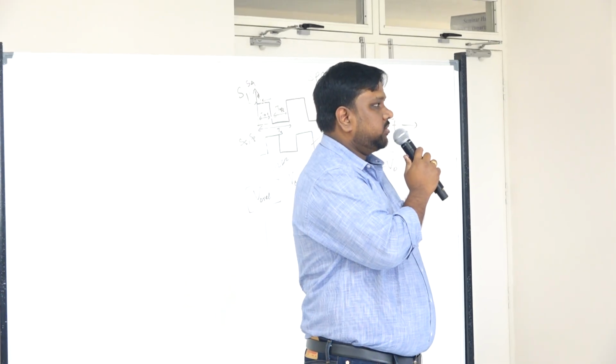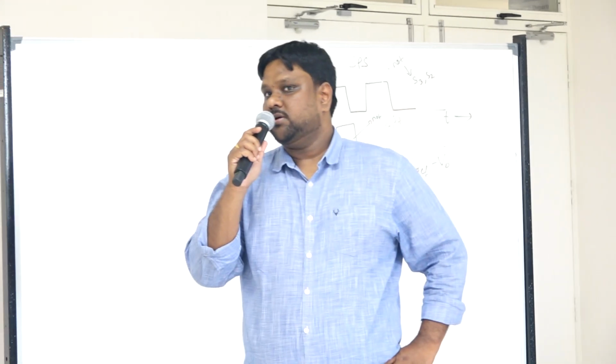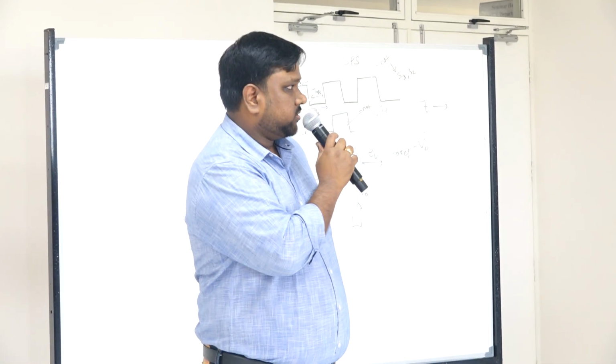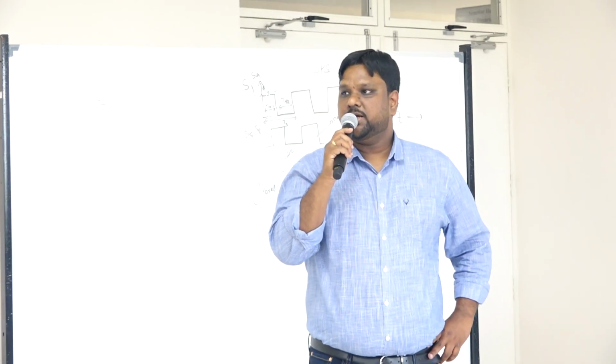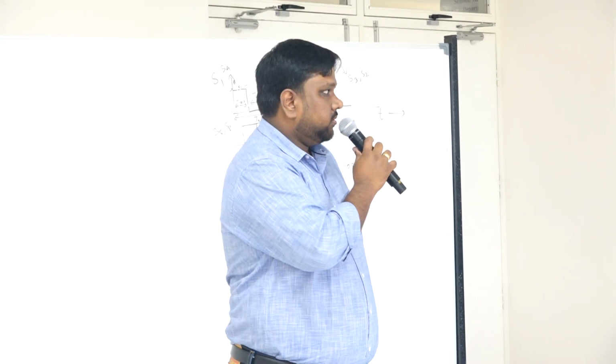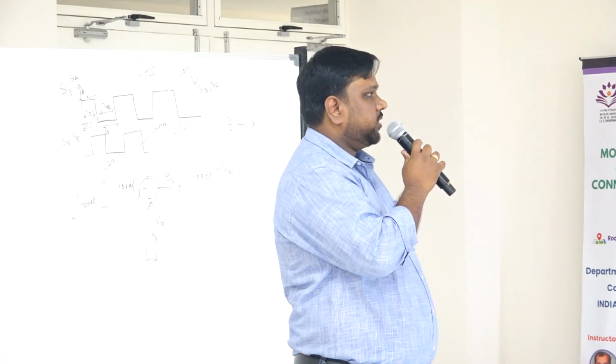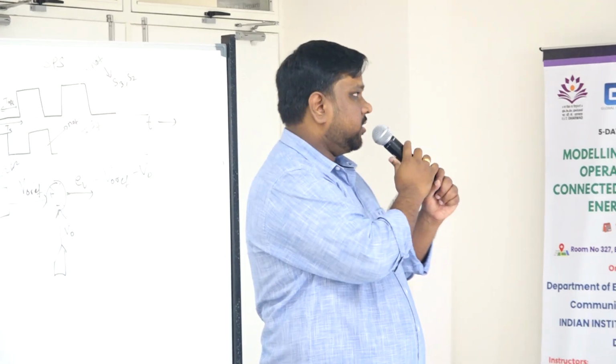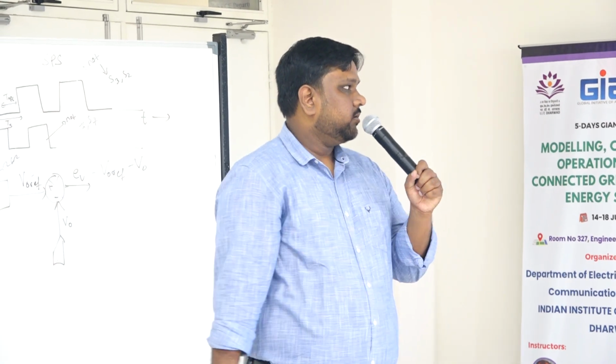So that U star is equal to B inverse. B inverse is your INVB in your .m file. It's basically a system parameter dependency. Okay, that is fixed. So B inverse into reference voltage derivative. V0 star dot means first derivative of the reference voltage, dV0 reference by dt, right? Now the second term is zeta 1 zeta 2 plus FL, and all zeta 1, zeta 2 and FL are defined here.